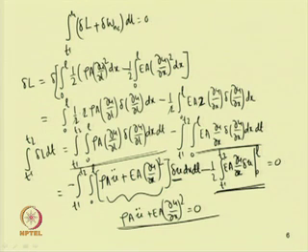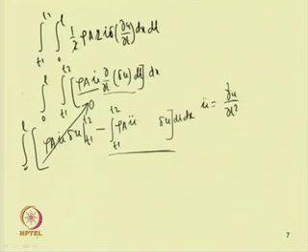While taking the kinetic energy term, one has to change the integrand. So, from 0 to L and T1 to T2, and then integrate it by parts. By integrating by parts, the first term becomes 0 and the remaining term one can take in the equation of motion.